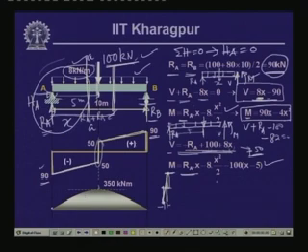Now, here if we substitute the value of x equal to 5 again, which is just after the concentrated load point, then this term becomes 0, R_A is equal to 90. So, 90 times 5 is 450 minus 100, this is again equal to 350. So, if you look into that, from both the expressions we get the value of bending moment at this point as 350.